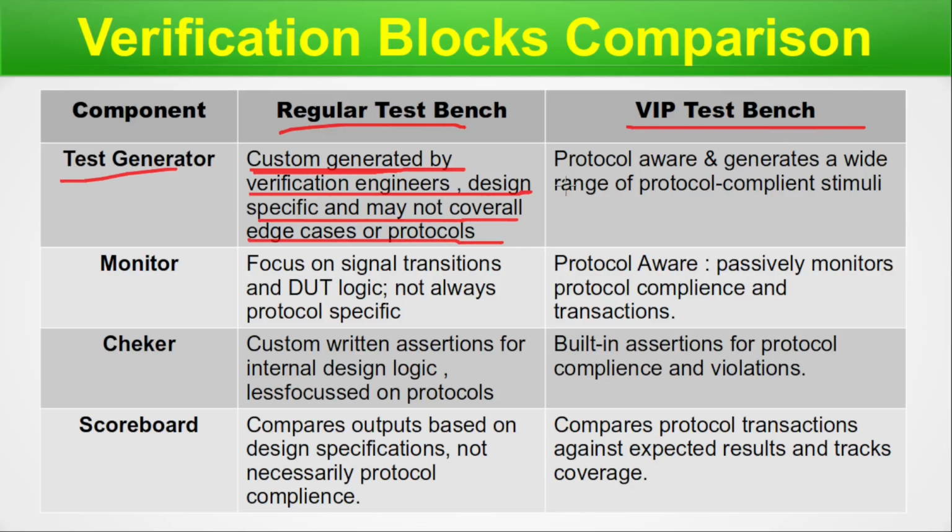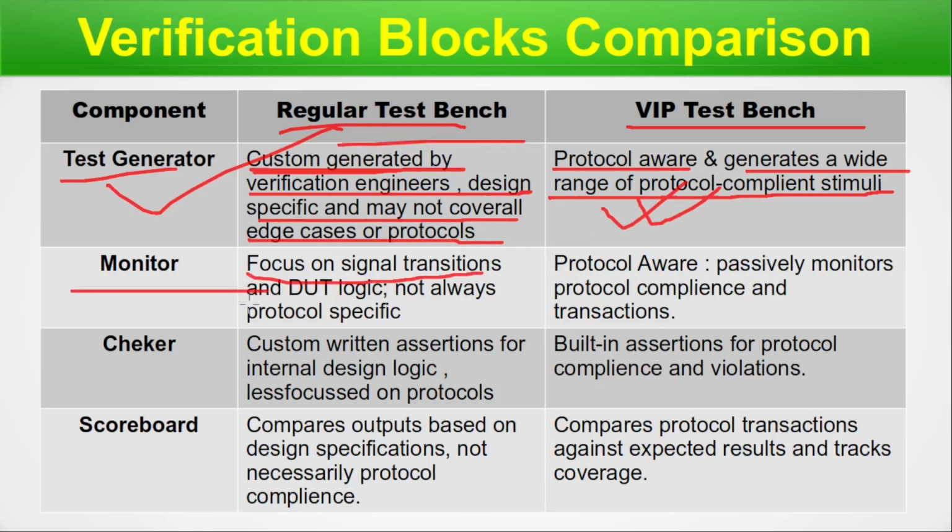Now the VIP test bench for the test generator, right? It is protocol aware and generates a wide range of protocol compliant stimuli. Now, as I have talked, USB and PCI, all these can have their own set of protocols for data exchange. Those protocols will be much more compliant in VIP with respect to a regular test bench. The monitor in a regular test bench focuses on signal transition and DUT logic, not always protocol specific. And here the monitoring is protocol aware, passively monitors protocol compliance and transactions. So that means we also have put a tab on the protocols here in the monitor.